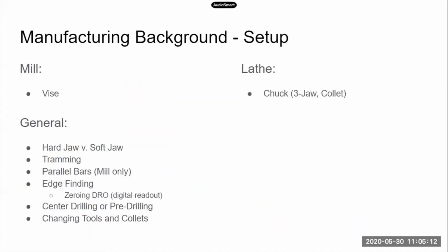All right. So now you have that base understanding. So you're going to want to set up your part on the machine. This is a huge consideration because you really need parts to be securely clamped when you have something spinning at thousands of RPMs, or even hundreds of RPMs. It's a lot of RPMs. It will fly if it is not securely clamped. So you want to keep that in mind during your design process.